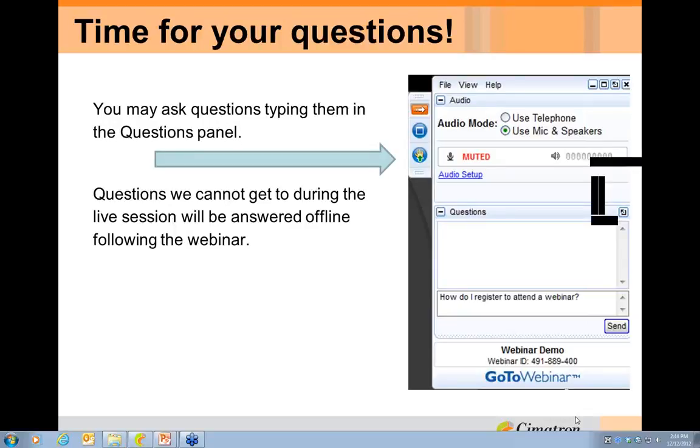Another question is kind of similar to that. Will the assemblies get too large if all of the revision parts are kept inside it along with the mold design? Yeah, that was actually one of my first concerns too about this. It's possible. We've got some customers that do very, very big mold designs, automotive parts, huge stuff. And yeah, we're keeping the part revisions in the main assembly, but they don't have to stay there. After implementation, after we've done our check, you can suppress those. And I don't think it's going to be a problem. By suppressing the parts afterwards, you can really keep the assembly size at a minimum.